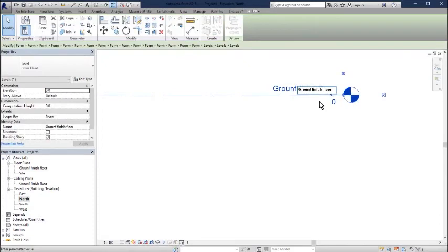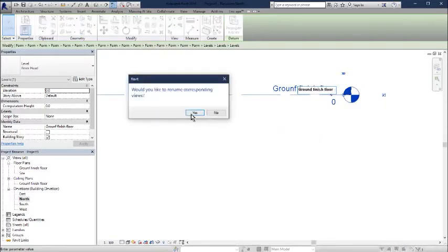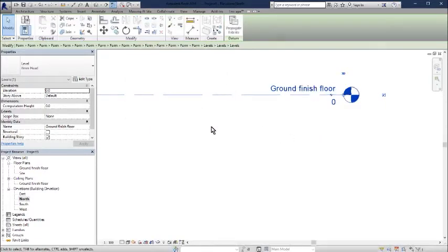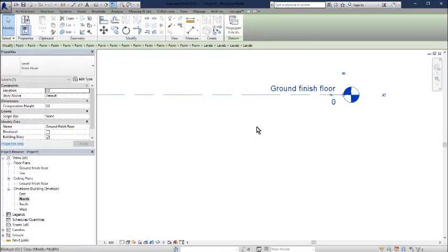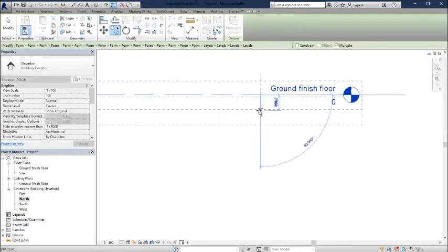What we want to do is to have our other levels as what we call empty levels, right? So those levels are just going to be used for referencing, and you won't necessarily see them come on the list of levels that you see in here on your left. So to get empty levels, all we need to do is just copy this level. So we're going to copy this level down, and we're going to go down about the thickness of our tongue and groove board, which is going to be about 50 millimeters.